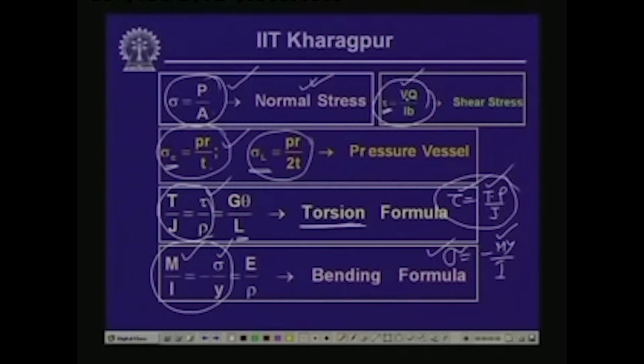Now, these are the individual cases as we have evaluated earlier. In this particular lesson, we are not going to derive any formulae, but we will make use of the formulae which we have derived earlier for individual load cases. Depending on the situations wherever we have combinations of these stresses, we will make use of those individual formulae and combine them suitably to arrive at the resultant stress in the member, because finally we are concerned with the maximum possible stress that can be generated in a member because of such combined loading actions.